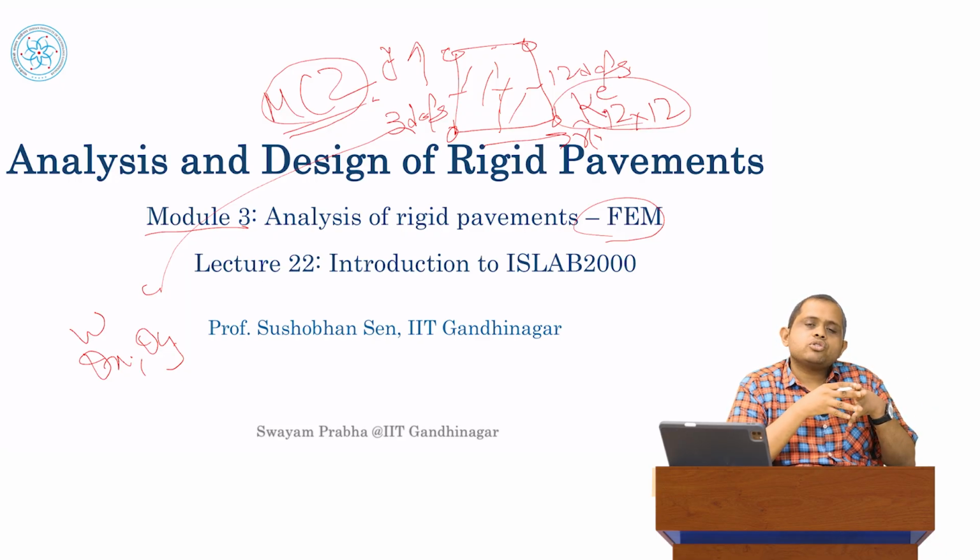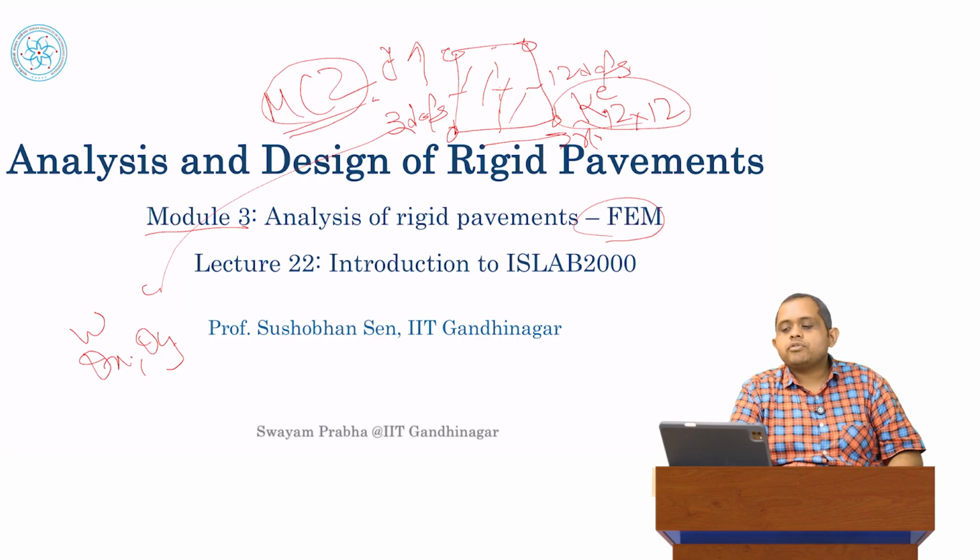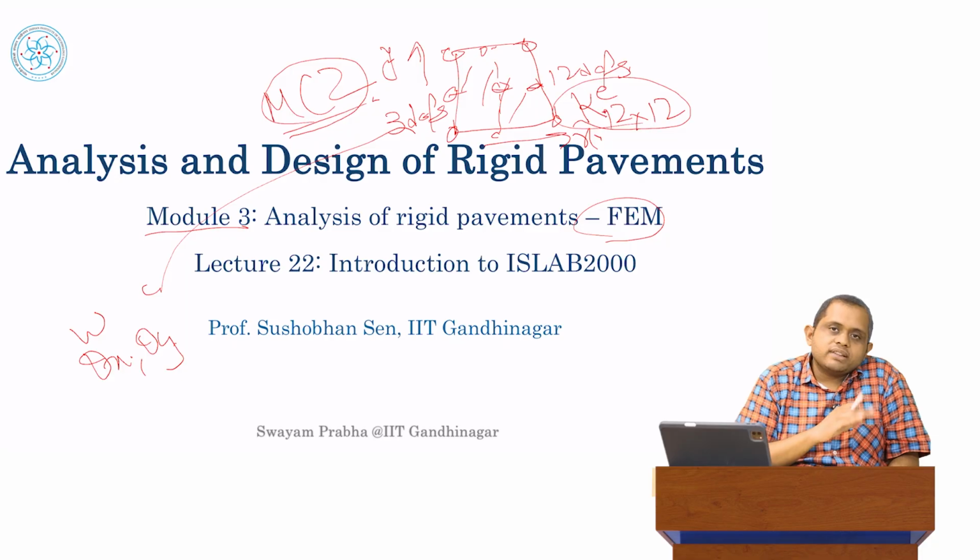But we make the assumption of local support, and we can assemble the local stiffness matrices into a larger banded sparse matrix called a global stiffness matrix. When we do that process of putting it together, we get a larger matrix called the global stiffness matrix. We can solve for it, and then we can solve for all the nodes that we have in our global system. So that was one thing we learned.